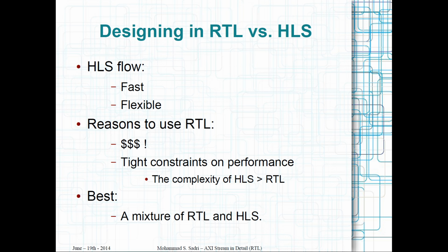When you use the RTL flow, you are nearer to the final hardware. So when you code directly in Verilog or VHDL, at the time of coding you have more control over what type of hardware is going to be realized after you create your module, while in HLS your control is at a lower level.